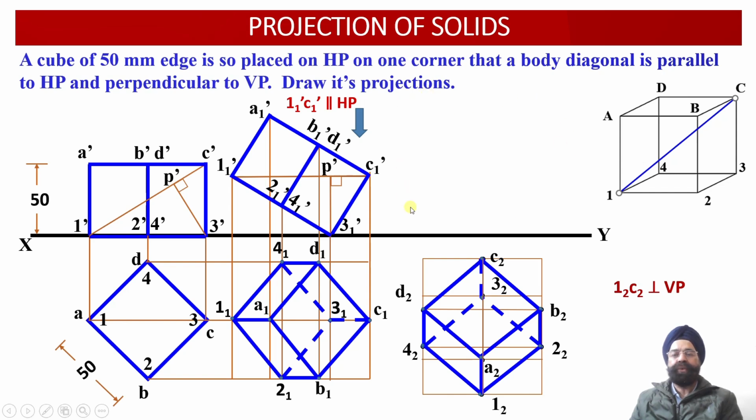So in the 6th iteration, we are required to draw the corresponding point. Now how many points were there? 8 points we have already located in the top view projections. Now these 8 points we are going to locate in the front view projections. How we can do that? From these 8 points in the top view construction over here, we are going to draw the vertical projectors through these 8 points. Now we are going to draw the horizontal projector lines from the previous elevation projection view.